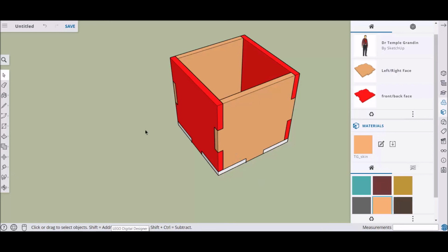So we could do that over where the tape measure is. If we click on it, the second one down is called dimensions. We click that, and this gives us a dot, and we can come across and click on points. So if I want to know how deep this box is, from there to there, I click on that point, click on the other point that I want, and then just move the arrow away. There you go, it tells me it's 80 millimeters that way.